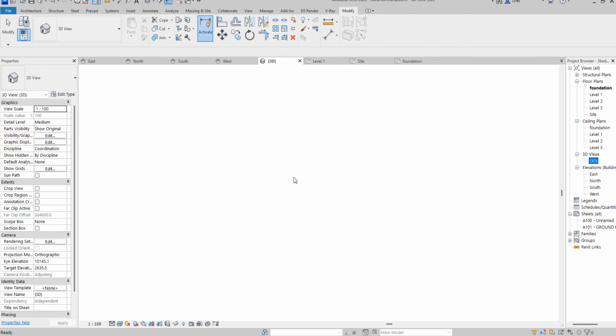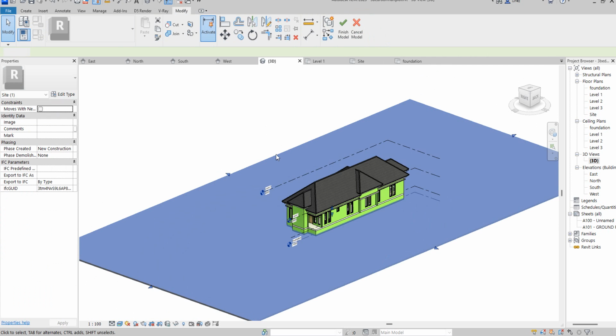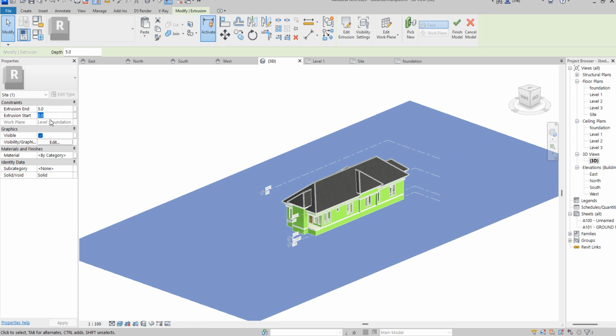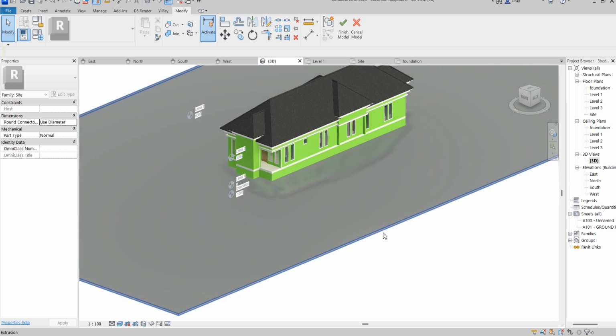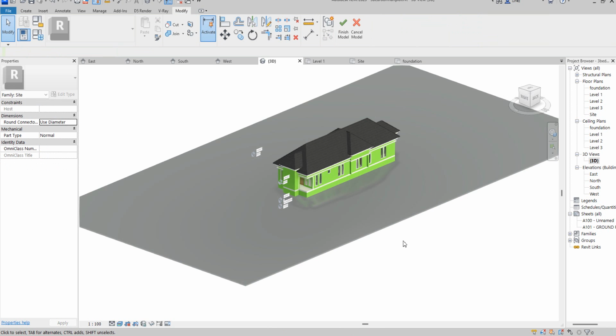So you can go to 3D and see this part has been there. So I will select it now, edit, and I will reduce the height of this because it's measuring 25. I'm going to use 5. Just want it flat. You can now use minus. You can create this one to be minus 20. So it's going to go down. Good. So every detail of this will come out. Or you can use 0 now since it's now minus. So you can just give it 0 so that you align with the base completely.